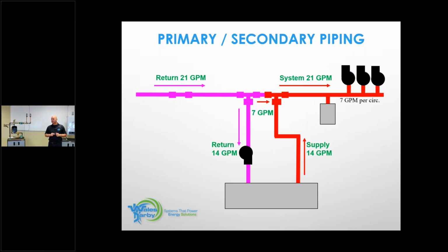Is it 160? We got one gentleman going for a 150. So a mix, right? 170, 150. 170 would be going the opposite direction because we're putting 140 degree water, and we're bypassing 7 gallons. So, as the one gentleman said earlier, a third of the water coming back mixes with the boiler water, which is 160, and we're going to cool that water off a little bit. So if you have, let's say on a design day, and your boiler is marginal, you may struggle a little bit on temperature here.